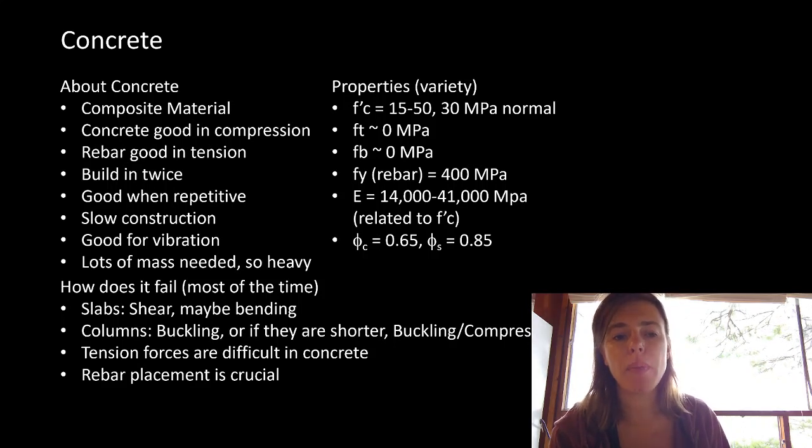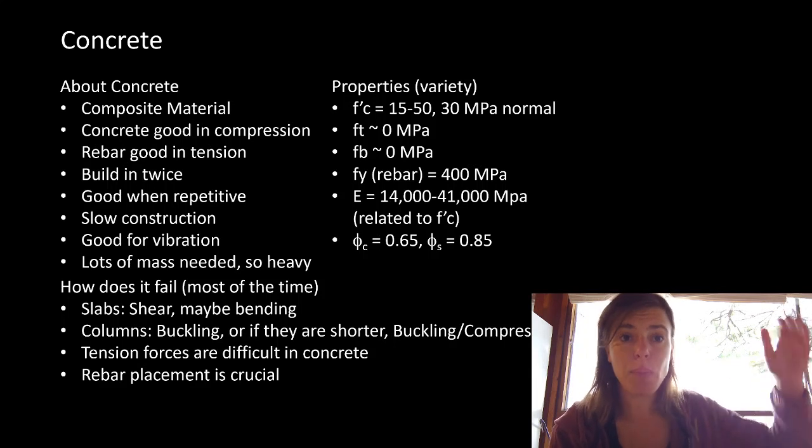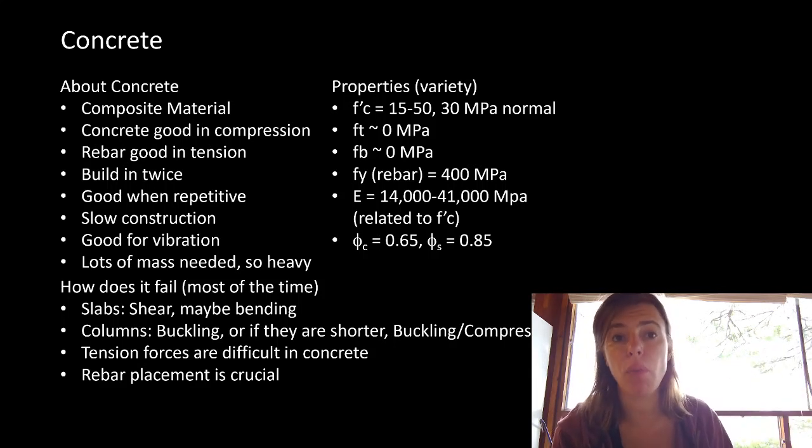And where concrete has a lot of value is when we can reuse that wood, what we call formwork. So we build the building, take out the wood formwork, and maybe it's a condo, and we take that same wood formwork and rebuild it on the floor above, and keep going up. So the more we can reuse our formwork, the cheaper our system starts to be. So again, it's great where it's repetitive.